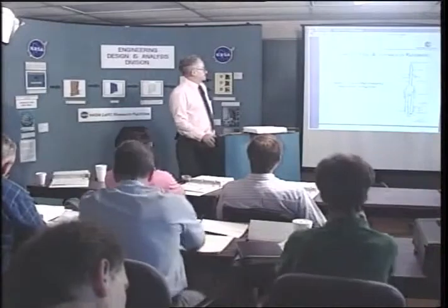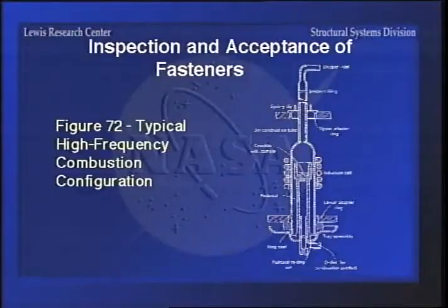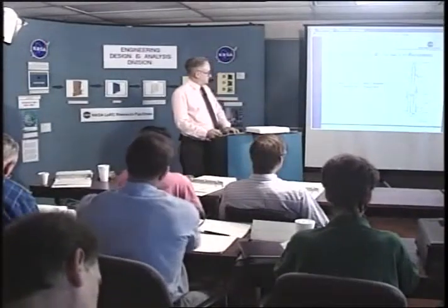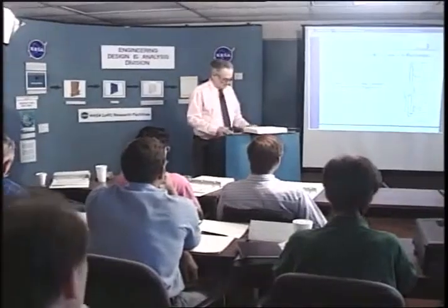Okay, we'll take a look at this furnace for checking the carbon content. You see, this is just an ordinary induction coil. You put the stuff in there, heat it up to about 2600 degrees with oxygen, and it will burn, and then you can proceed.